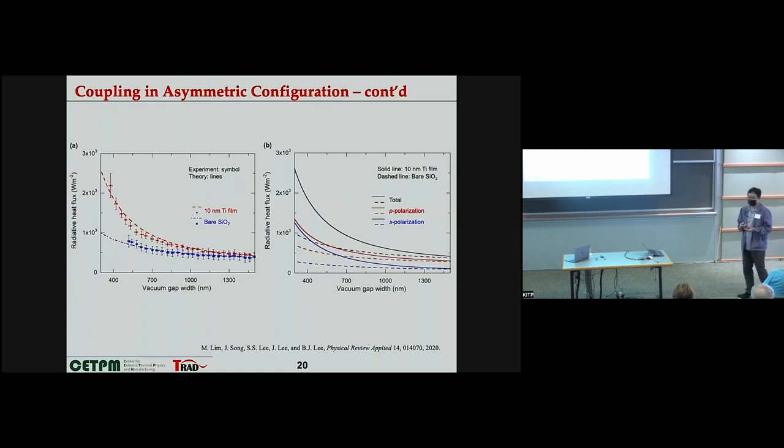In S polarization, we also have enhancement due to the so-called thin film effect, basically an interference effect inside a very thin film, as well as the thin film having greater loss because of the electron boundary scattering effect, and that will change the sharp spectral radiation peak to be broader, so that overall heat transfer can be enhanced.